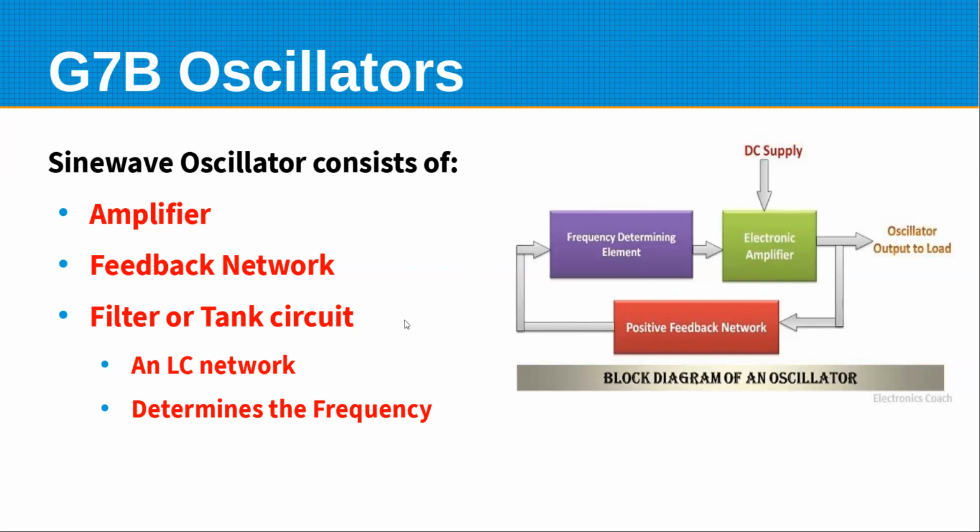And I think they called it a tank circuit because you're storing energy in the inductor and the capacitor, and this is going back and forth from the capacitor to the inductor at its resonant point. So as long as you're making up for the loss in energy from the transfer, it will oscillate forever.